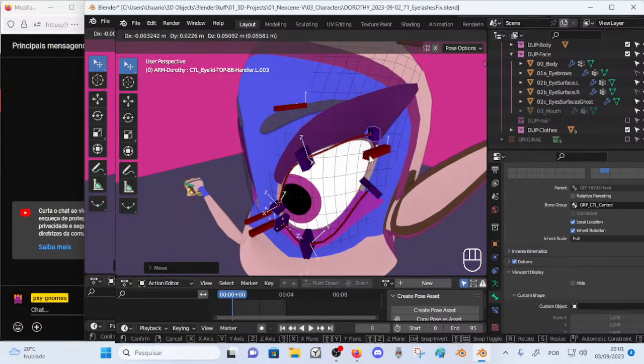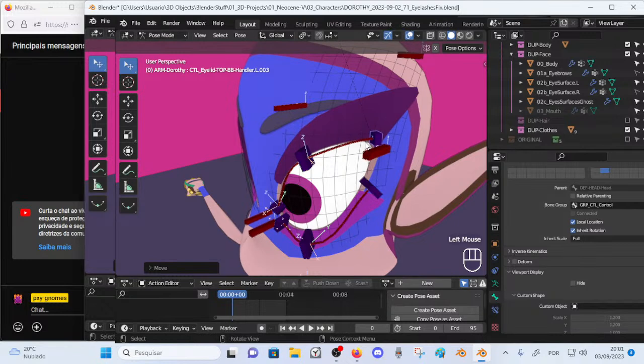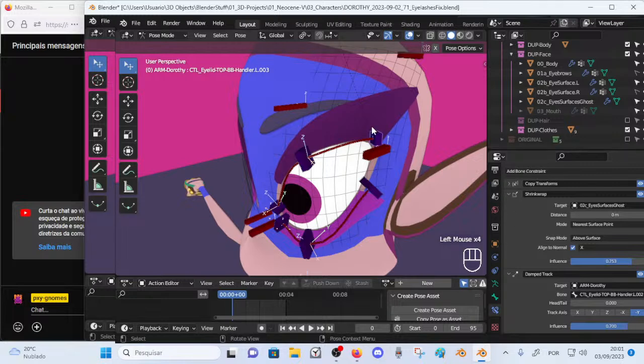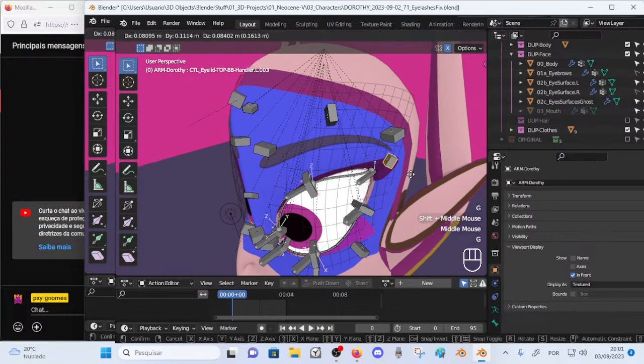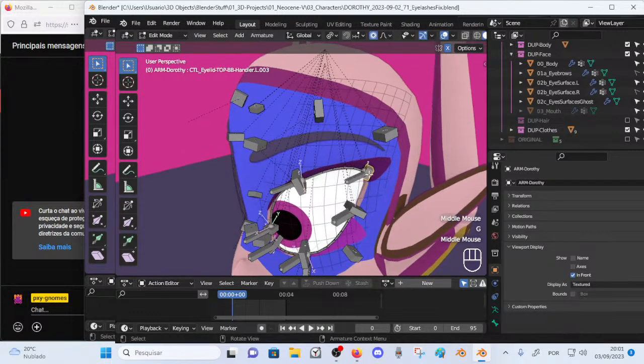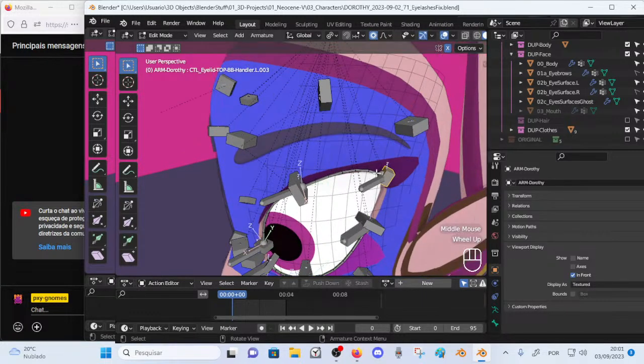Now it looks to be slightly smoother, but no, nothing to do with deformed bone. But it is a bone that is parented. Okay, it has the parent to the head bone. Okay, you see, it's a target of a stretch to bone constraint, because it's a bendy bone spline, this thing.